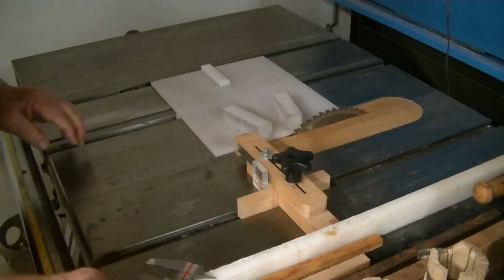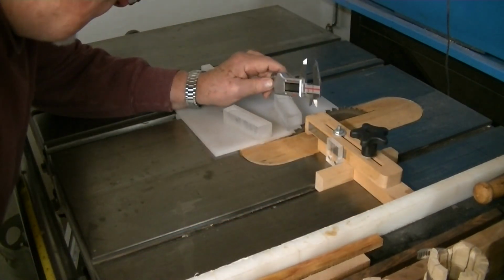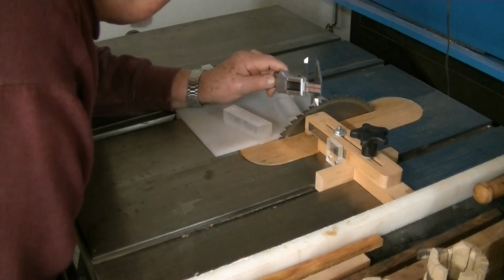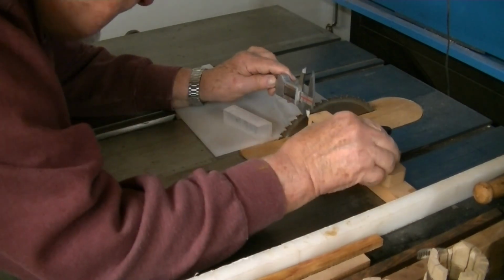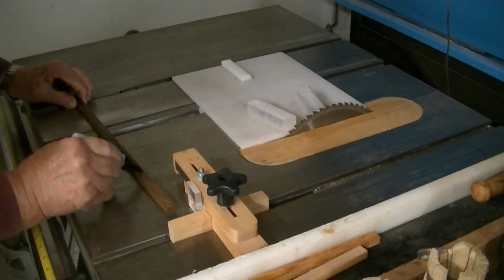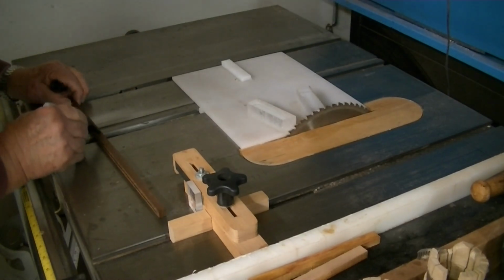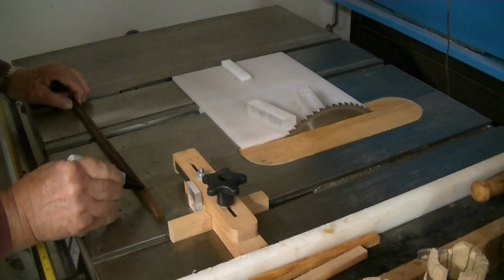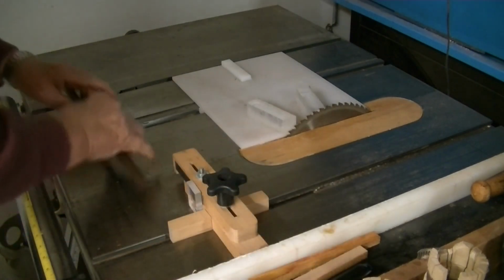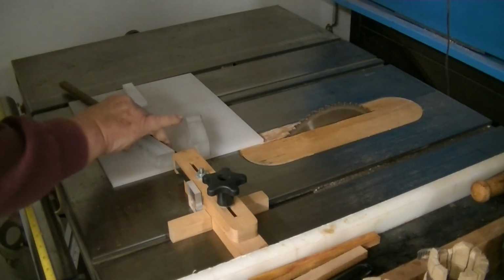So here's how I cut and build one of the rings. So what I'm going to do is I'm going to set the segment edge length for the segment I'm getting ready to cut here between the saw blade and the stop. I'm marking a piece of wood with a line on its top and on its front face. This will allow me to keep it oriented properly on the wedgie sled that I've created there, the white plastic device. This will allow me to cut 12 segments very accurately.